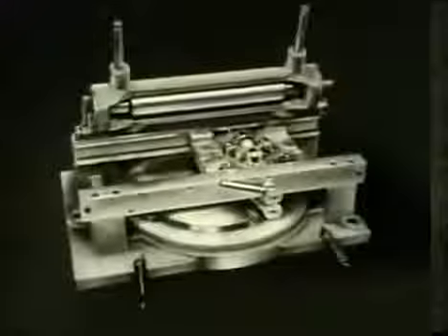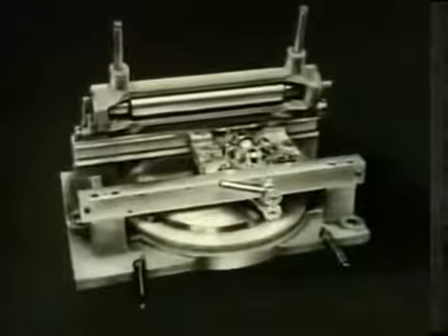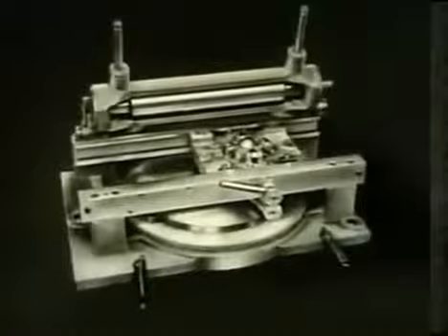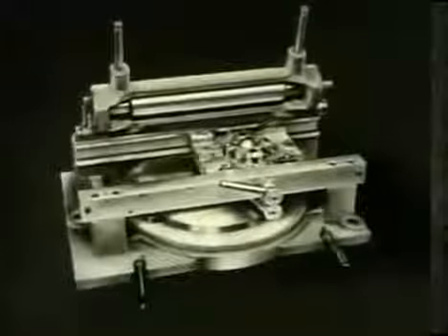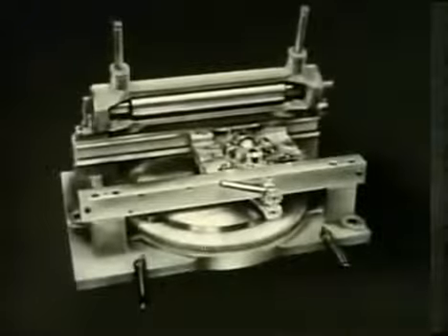This is a disk-type integrator, one of several different types. They can do many jobs. One of the simplest, the job in range keeping, will give you a pretty good idea of what an integrator can do. An elementary example of range keeping is one with stationary target and with own-ship moving at constant speed along the line of sight. The problem starts with an observed initial range.